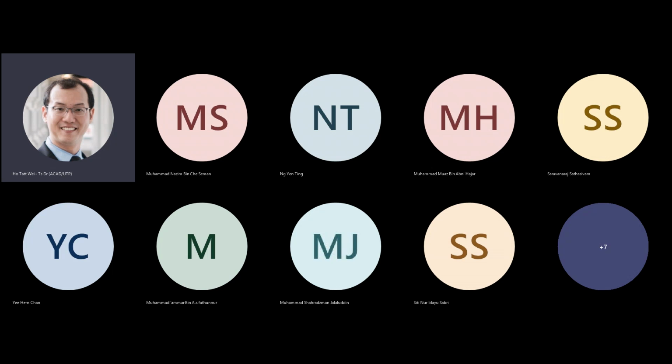So it is not an AND gate, which means that this is the logic. Your AND gate, when two of them are logic 1, you usually get logic 1 here at the output, and everything else zeros. But this is not an AND gate. It's the opposite of an AND gate. So this is the logic level, right? So we must find a way to devise a circuit where when both the inputs are logic 1, that means the switches are closed, the output will be connected to 0.